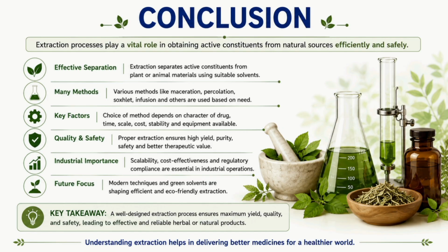operations and desired concentration. Before we finish, answer one question. If a drug contains a heat sensitive active constituent, would you immediately select the Soxhlet extraction? The answer is no. You first consider a suitable cold extraction method. That is the scientific decision making.